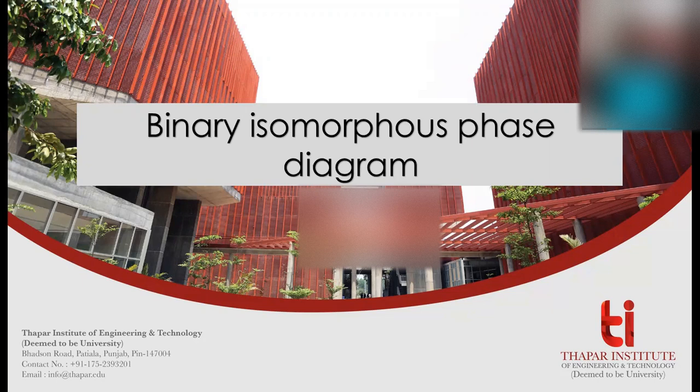But the word isomorphous makes it distinct from other phase diagrams. Isomorphous also means they look the same in all directions, meaning compositionally. So I can say they are also known as solid solution phase diagrams. They are solid solutions basically. When you mix the elements, you cannot identify them. They behave like solutions. Like we have liquid solution, gas solution, same way we have solutions in solid also.